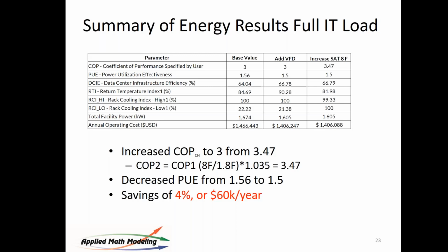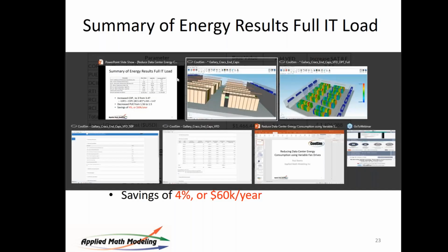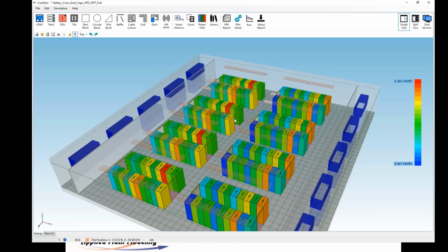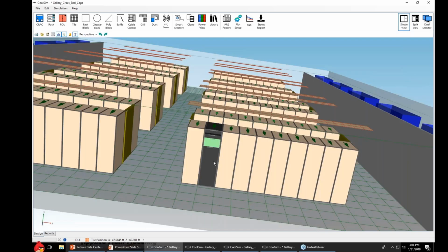What is the standard CFM per kW? CFM per kW, in this case, we're using 125. Again, it does depend upon what you're using for a delta T. So let me just see if I've still got that interface open, and I'll show you that one more time. Not that one. How about this one? This is the one I had open.